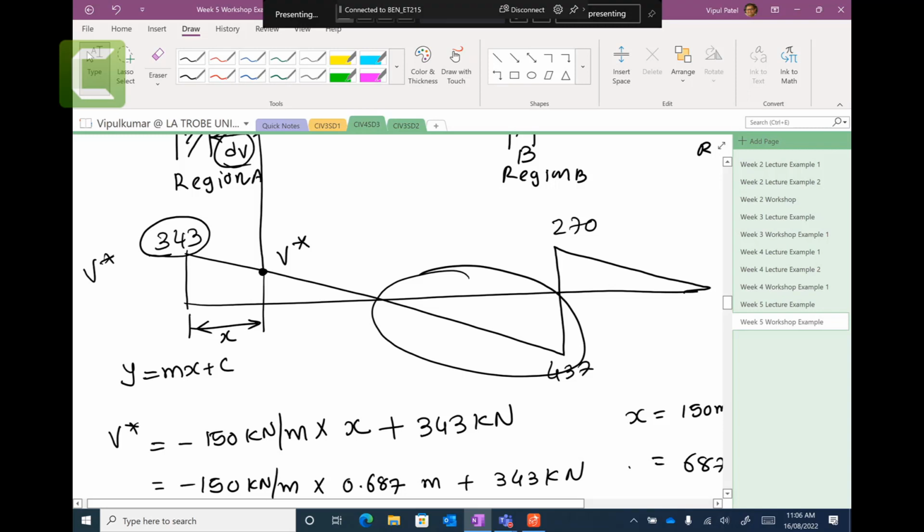And you have a multi-story building, and you need to have a balance. When you put the spacing, you don't need to put 156, just do the 5 mm increment or 20 mm increment. It's a rule of thumb.